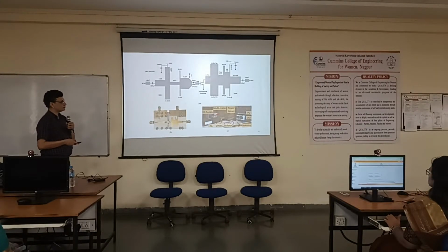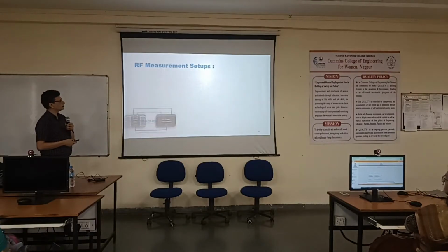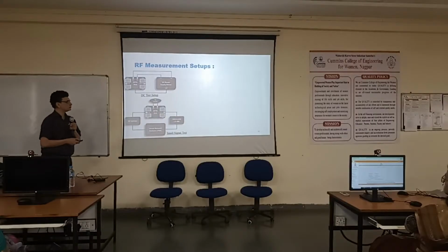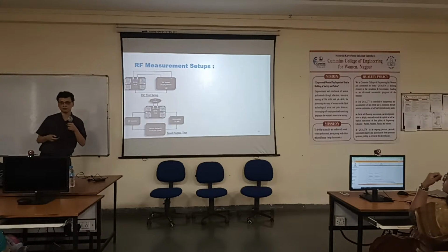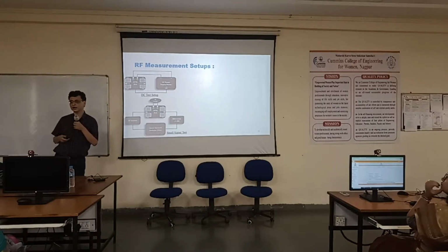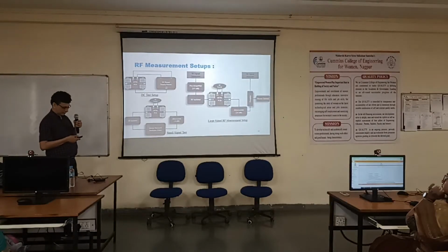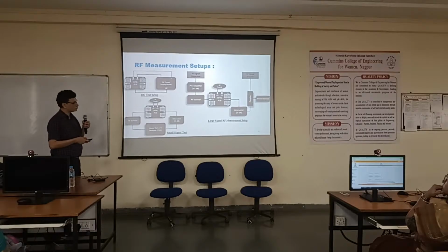And finally, this is the fabricated power amplifier. This we tested in our lab. We tested it three ways. One was a DC test, using a multimeter where we just test what are the DC voltages and currents. Then this was using a VNA. The VNA does a non-linear measurement. It calculates the S parameters, which are just the non-linear. It doesn't take into account harmonics. And the third step was to do a complete harmonic test with actual input signals and actual output signals.